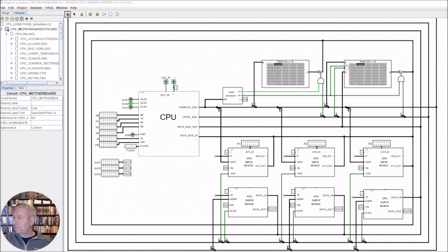And of course we're going to have our address bus here as well, and we never talk through this. Address bus is here is for the ROM, so we'll have the address bus for the ROM and the RAM. But remember, we're going to have 16 bits here, but we're only actually going to be addressing a 2 to the power of 15 for the RAM, which is a 32K. So it's expecting to find a 15-bit value coming in. So that's why we've pulled this off, and we've separated this into 2 outputs.